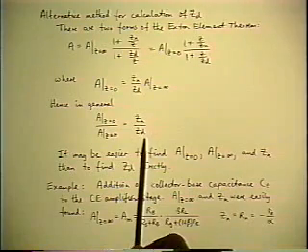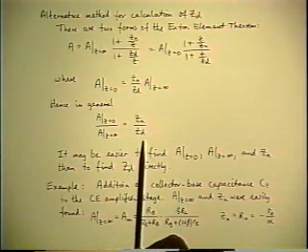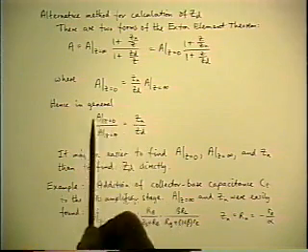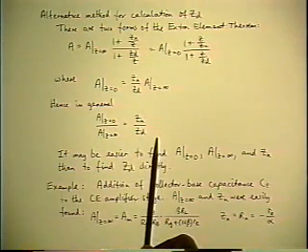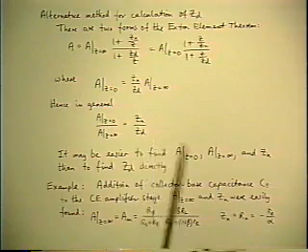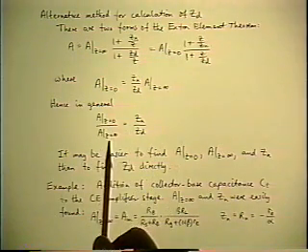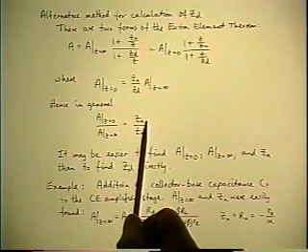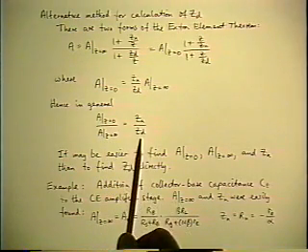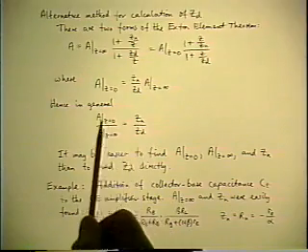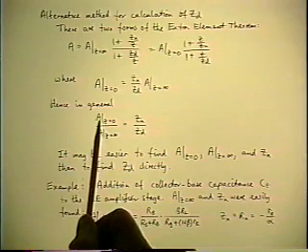Calculation of the Zd may get more difficult in more complicated cases. Now, we have an additional piece of information, the redundancy information, which suggests that since we know one of the reference gains and Zn is easy to calculate, instead of calculating Zd directly, maybe it would be easier to calculate the other reference gain.